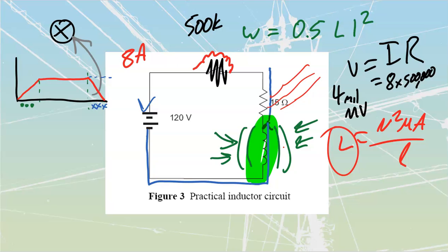If you've worked with a barbecue sparker before, or an electric stove, you've probably heard an inductive circuit at work, that tick, tick, tick sort of noise that you get whenever one of these is sparked up. It's simply an inductive circuit that is opening and closing, and every time it's trying to maintain its current across that air gap, because that's going to be the easiest place for it to put it across, and that's what creates our sparks inside of there. We will refer to this as inductive kick.